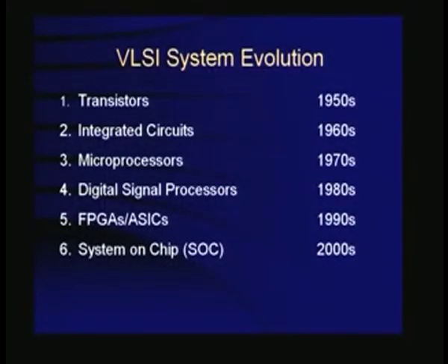And then digital signal processors became a new family of processors. The difference between microprocessors and digital signal processors is that digital signal processors have some specific functions that can be performed with them which are not possible using microprocessors. Like there is a hardware multiplier. A microprocessor may not have a multiplier. Even if you have a multiply instruction, it is performed by some sort of a microprogram, whereas a digital signal processor has a hardware multiplier and has other features like Harvard architecture and all that.